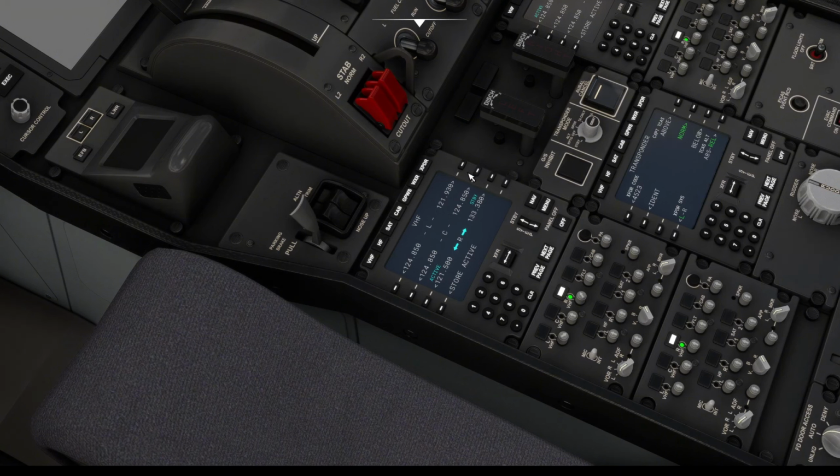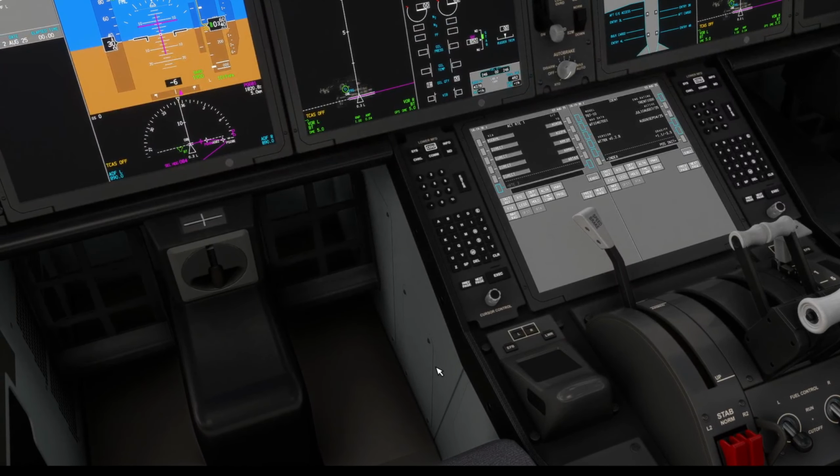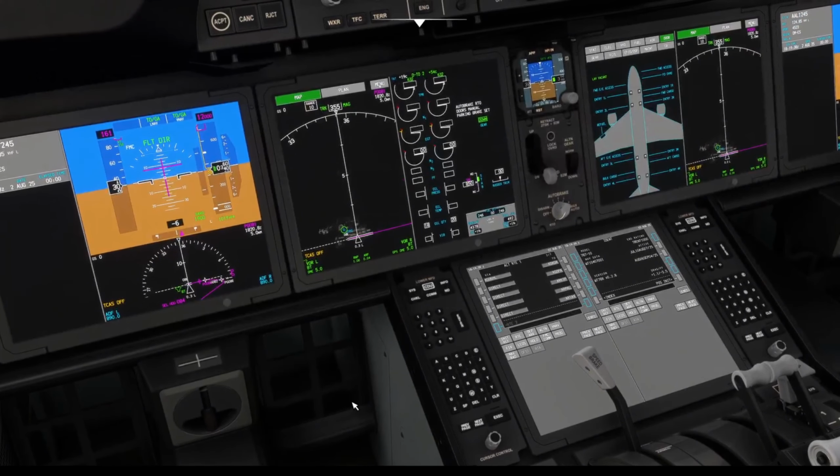If not, you can already pre-select tower frequency, and then when you are on tower, basically you put in your airborne frequency and you put it here on standby. And you would monitor the right VHF, so you could listen to basically guard. The frequency is called guard, so you would hear if somebody is in distress or whatever is going on. So that would be the setup, and then it would be time to perform a briefing.